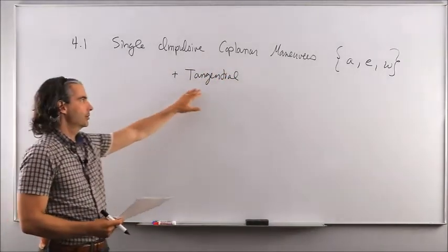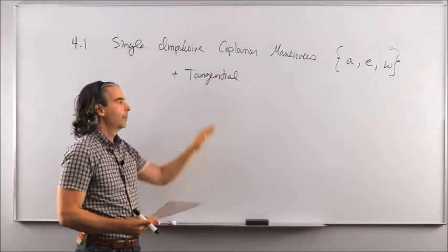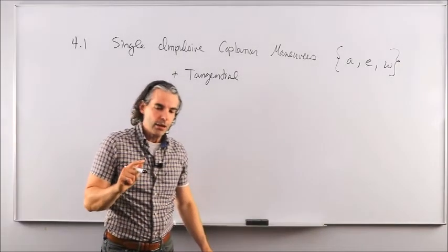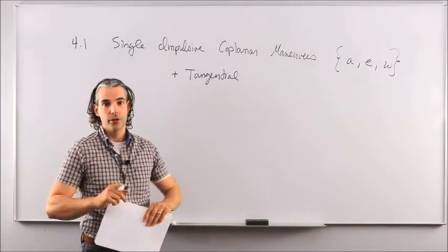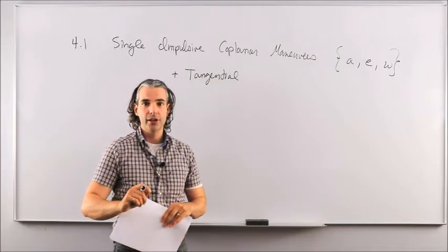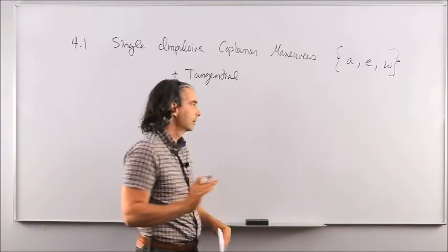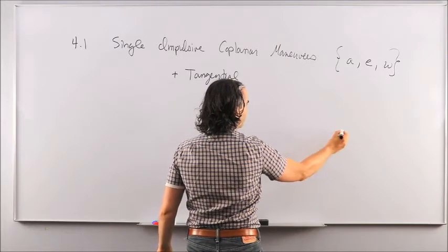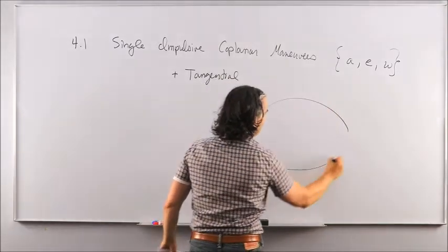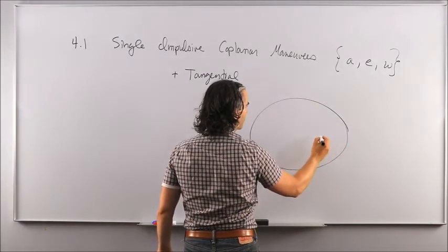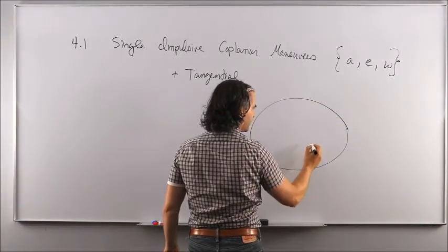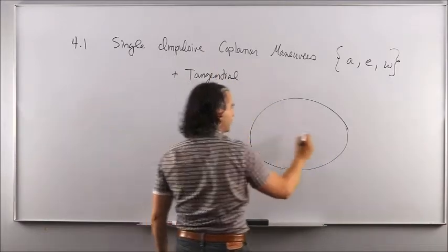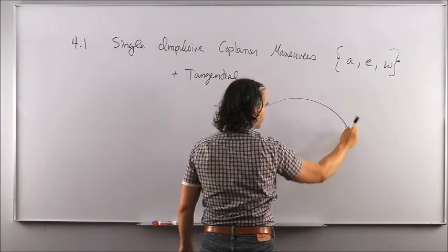That assumption will also get relaxed down the road, but to begin with, only tangential maneuvers will be looked at, i.e., maneuvers that will only stretch or compress the velocity vector without changing its direction, okay? Meaning that we need to find a location along the current orbit and the final one where both orbits intersect, obviously, because of the impulsive assumption, but tangential meaning that we're not going to change the direction of our current velocity vector.